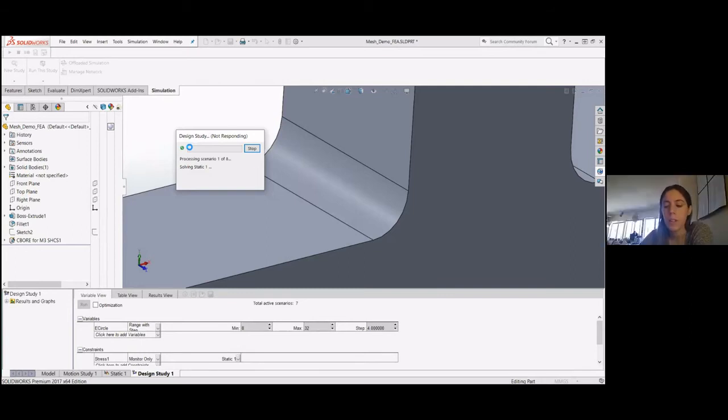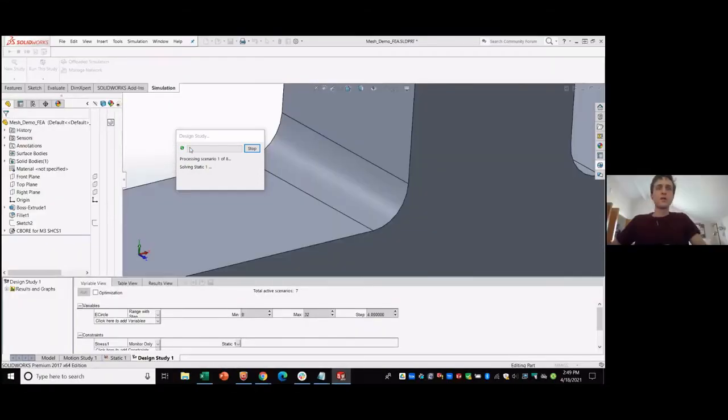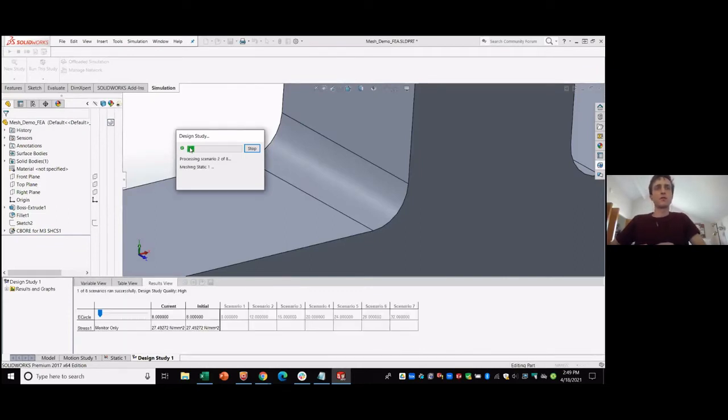Are the elements in the mesh tetrahedrons, or are they just two-dimensional, like across the surface of the model? They are tetrahedrons. And in fact, if you look into this a little bit further, they are tetrahedrons with mid-side nodes. So they're not perfect tetrahedrons. They actually capture the curvature via having a node in the middle of each edge. It does enable the model to be more accurate for the same number of tetrahedrons, and it does solve faster.